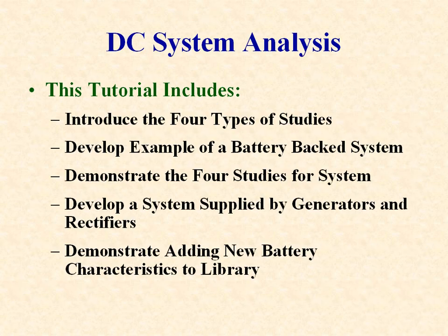This tutorial starts with an introduction to the 4 types of studies that can be performed by the DC System Analysis module. The tutorial will continue with the development of a model for a simplified battery-backed distribution system. We will then demonstrate each of the 4 types of studies, including battery sizing, load flow, and 2 methods of